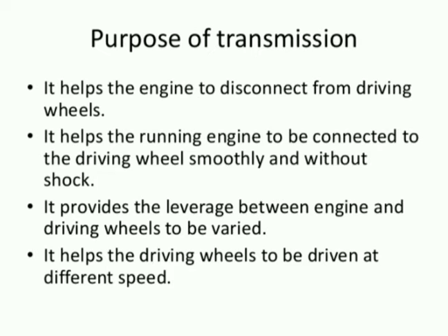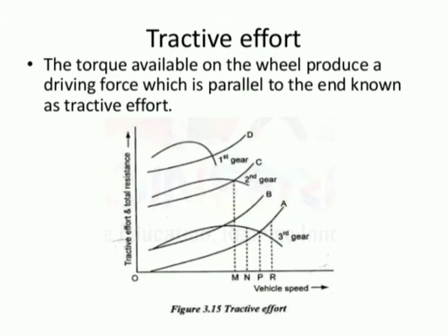The purposes of transmission are: it helps the engine to disconnect from the driving wheels, it helps the running engine to be connected to the driving wheels smoothly and without shock, and it provides leverage between engine and driving wheels to be varied.